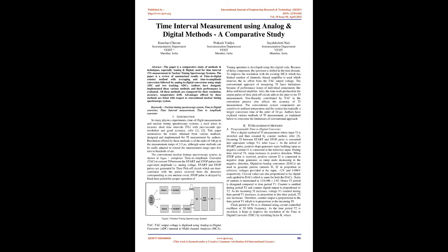The paper is a review of summarized results of the time-to-digital counter method with averaging, and time-to-amplitude conversion followed by analog-to-digital conversion using a single ADC and two tracking ADCs. Authors have designed and implemented these various methods and their performance is evaluated.